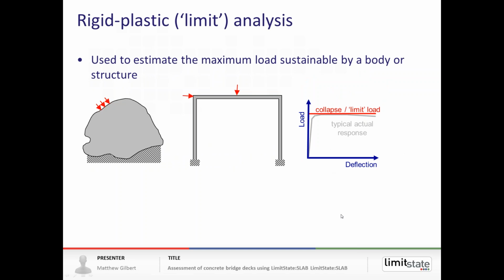When I say rigid plastic analysis or limit analysis, what do I mean? Well, I mean that whereas with elastic analysis we assume that Hooke's law is valid ad infinitum, here we neglect elastic strains and we are simply interested in the plateau, the collapse state, and we apply that whether it be a solid body or whether it be a structure.